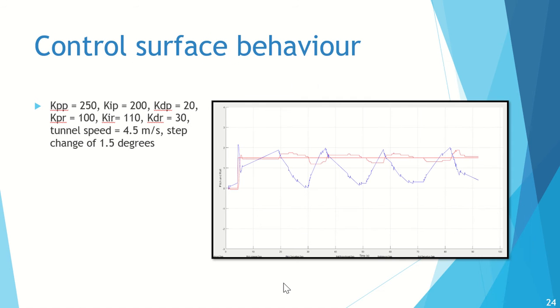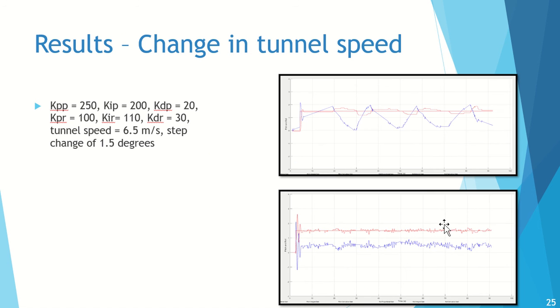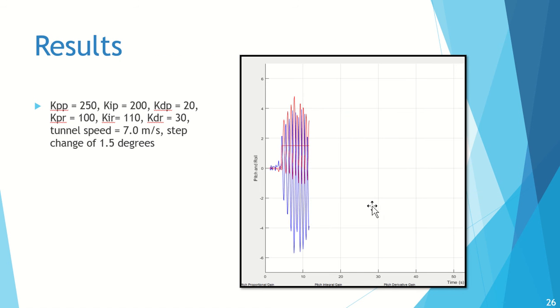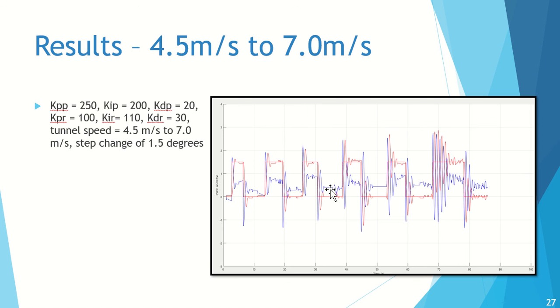You can look at the linearity of the system by looking at that. You can also look at the control system behavior, or the surface, how the elevators move and that sort of thing, and the effect on tunnel speed. Sometimes if you design it incorrectly it can go unstable, and it'll start rattling around quite violently in the tunnel, at which point probably you want to switch it off, otherwise something will probably snap off and break.